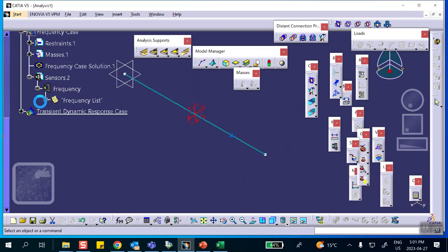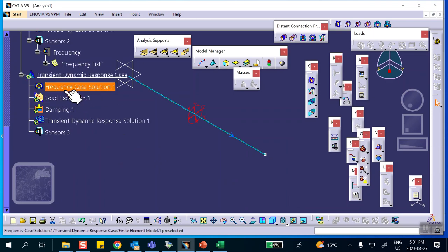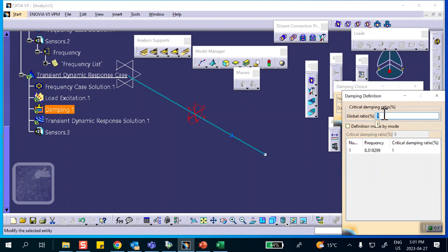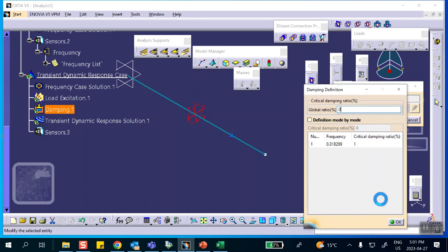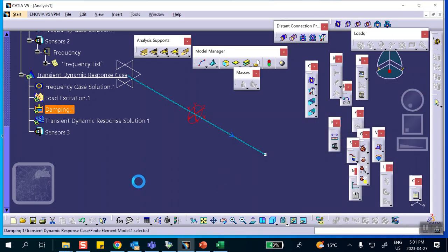You say, okay. Now, first of all, if you go here, we have done several videos using these tools. So if you go to damping, double click on it. You click on the wrench, it automatically puts 1% damping on all the modes. There's only one mode here, so we make that 0 because our problem is undamped, right? Okay, good. That takes care of this.